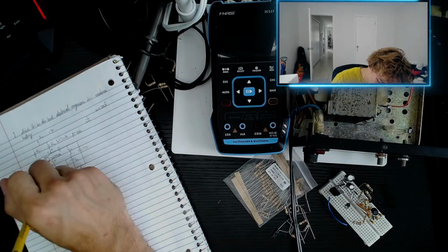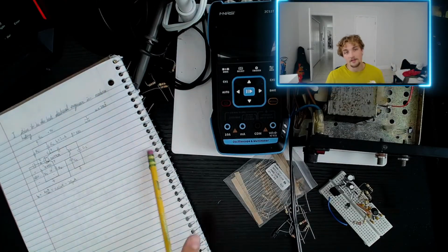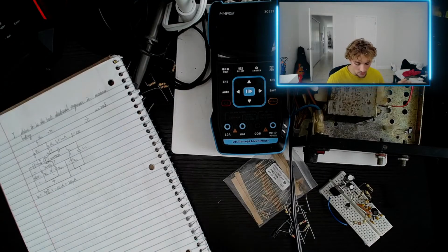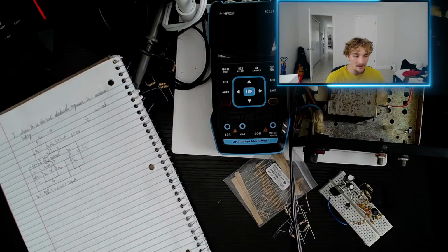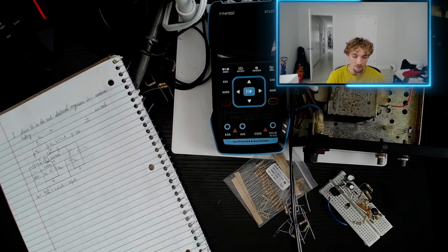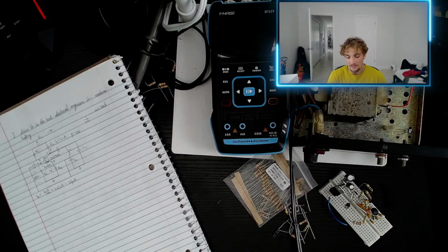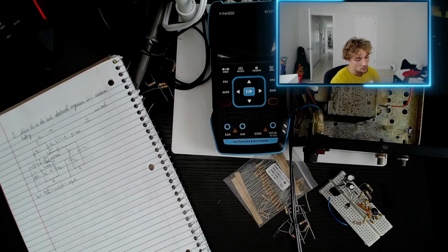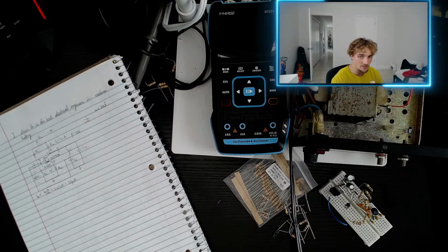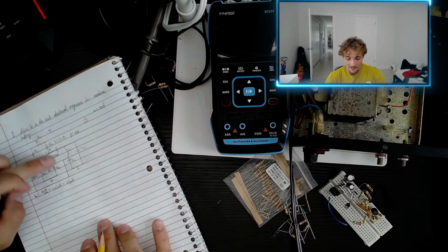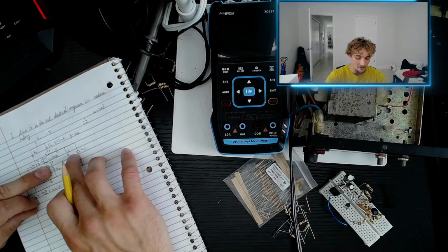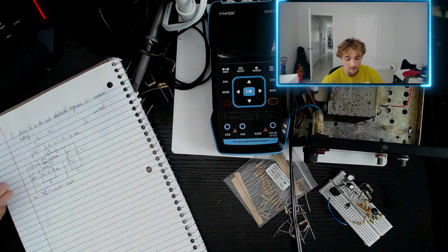Now, another practical application, something that you could perhaps derive from the physics of everything, but we're not going to take such a deep dive. We're looking at the practicality of it, and this is an assumption that's common throughout designing Colpitts oscillators. Considering that we're using a common emitter amplifier, that's this stage of the circuit, and this stage is what defines it as a Colpitts oscillator, how we're tapping in between the inductor and the capacitor, right?